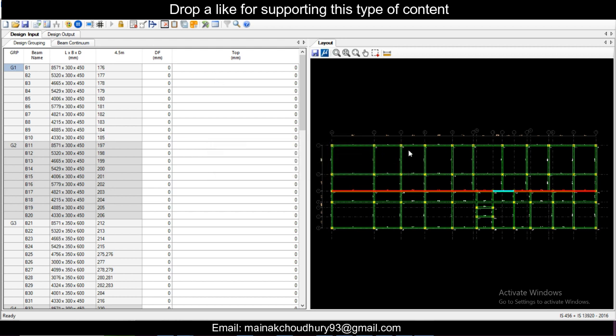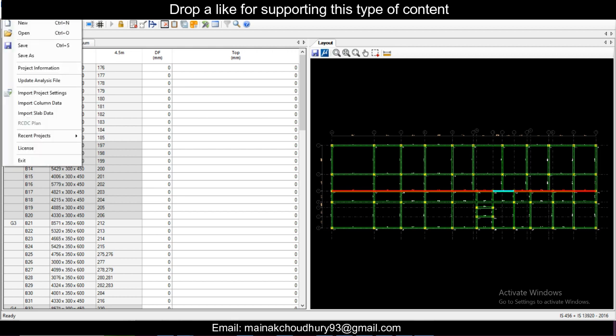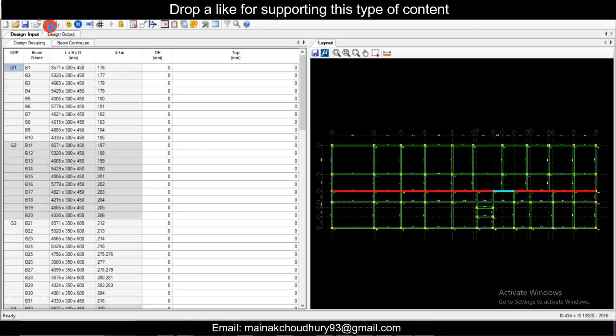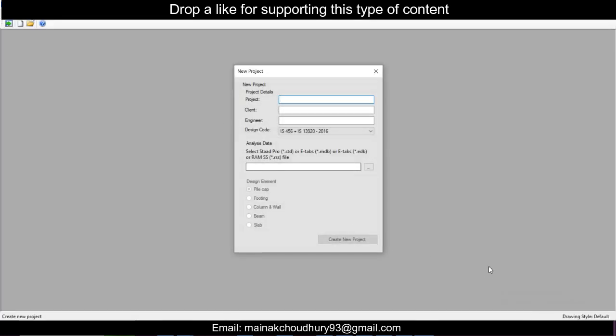So for the terrace beam, everything will be the same, but there are lesser loads in the terrace beam because there is only the parapet wall and all. So let's see if there is any difference. If we can go for a lower section, I think we can. I think the section will remain the same, but the reinforcement can be changed. So let's try this out and click on new, and we'll fill up the details. This time we'll select 9 meter.